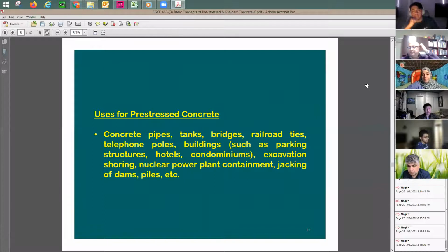All right. Do they check the uplift, or do they just go? The camber. Yeah, the camber, absolutely. Especially when it comes to final deflection analysis, this camber is going to be subtracted from the total deflection. So this is what's also good about pre-stressed beams, that you have this camber, right? Yeah. So it's going to save you a little bit of the deflection.